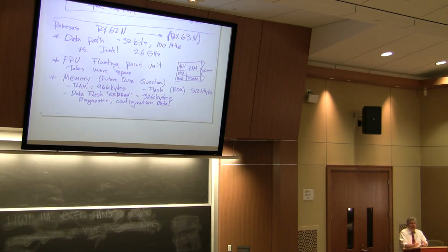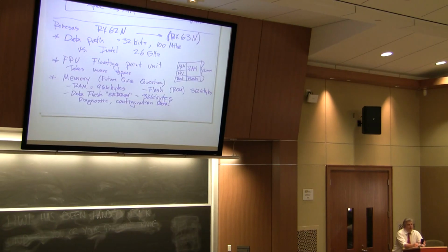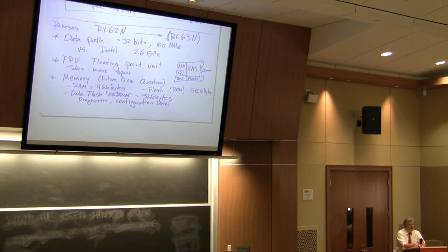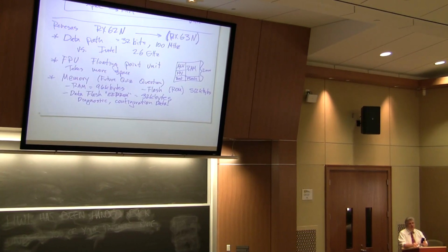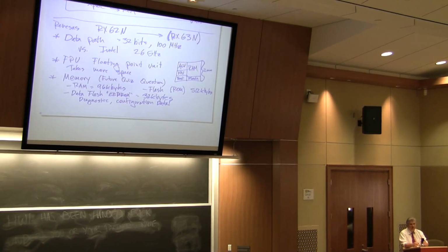So imagine this. I'm running a program on my new device that I'm designing, my cell phone. And I want to make sure that if something goes wrong, I have at least stored information of what was going on. In other words, what state was I in, what type of code was I running, etc. So maybe I will write off into my EEPROM or my data flash some additional information just as I'm about to reset my phone or my device I'm testing. So that would be another thing that you'll do in data flash.